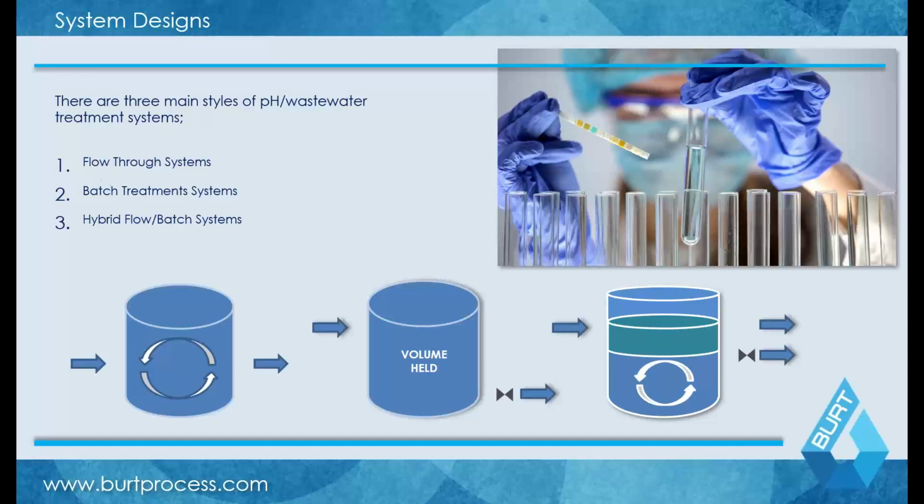And if you have very specialized waste streams, or if you're trying to tie the pH system into other treatments, such as effluent decontamination or a precipitation process, if you're treating, for example, HF, batch is predominantly where you're going to be because you have a much longer and much more reliable method of treatment in those cases. The downside is batch treatment processes greatly reduce your throughput.